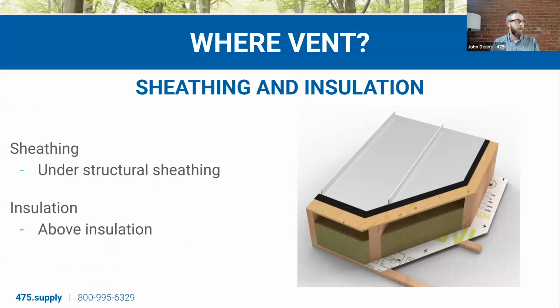So where are we venting? And this is like one of the small code references here. The code wants you to be venting under your sheathing, again, because we want to give that sheathing a surface to dry, and above the insulation. So you want your ventilation channel to be outside of your insulation and under your sheathing. The code basically requires an inch or more in that cavity. At 475, we recommend at least 2 inches for that vent channel. But again, reference the code in your area and build accordingly.